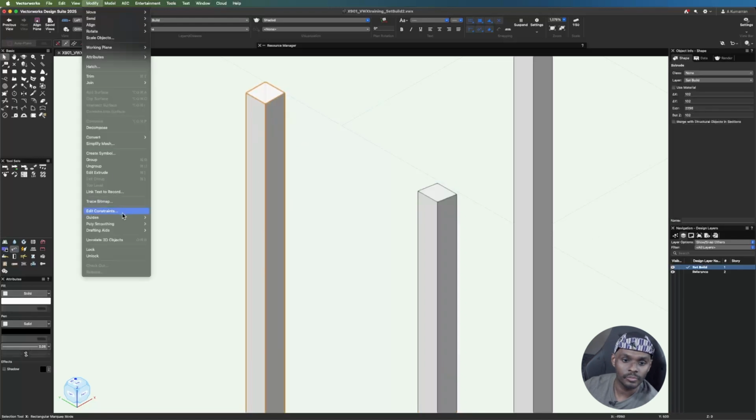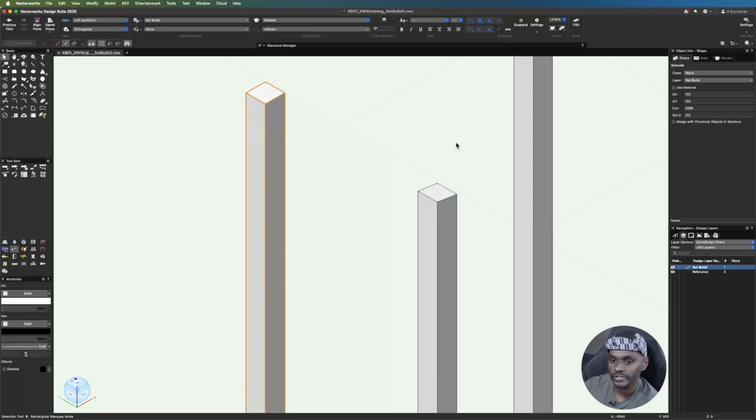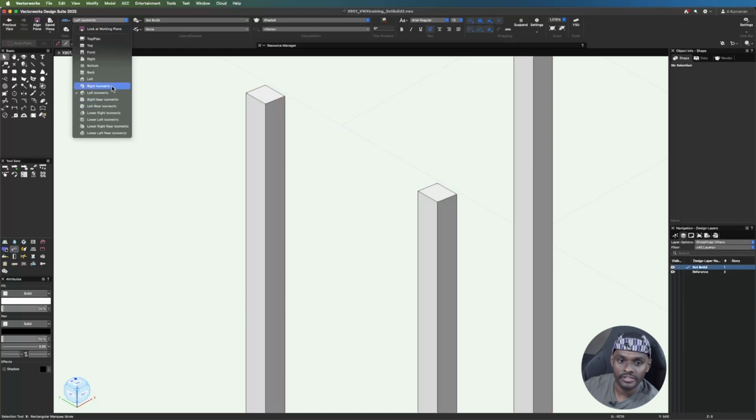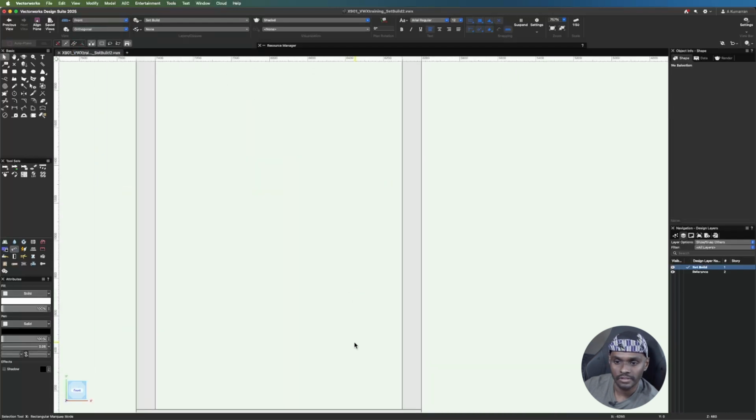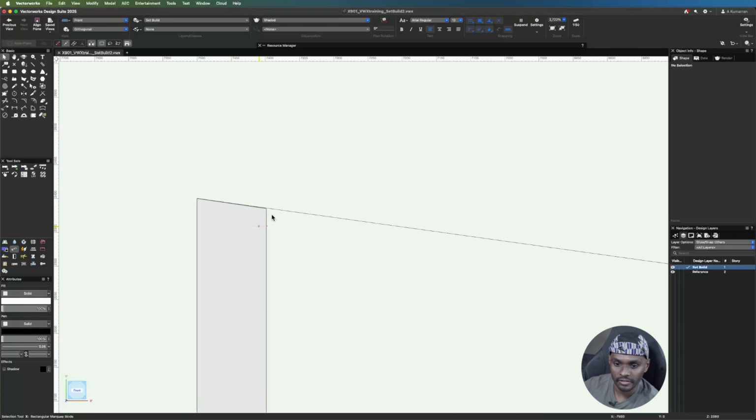This is also going to be converted to a mesh, and I want to move along to find the point I want to adjust and drop the height by 15. Move along again and drop this height by 15 as well. So if I were to switch back to my front view now, you can see that the mesh does line up with that 8-degree line that I have.